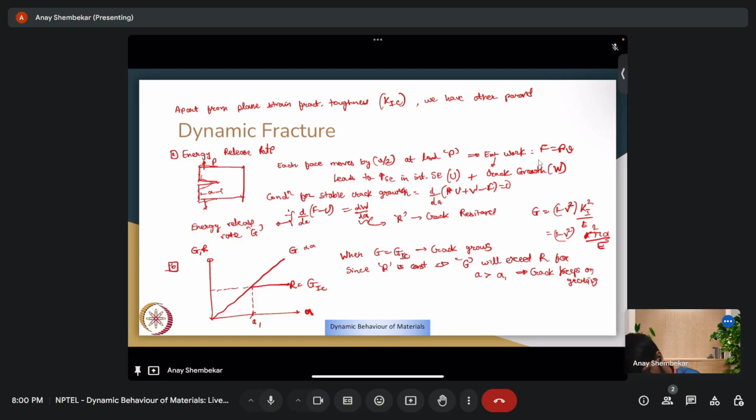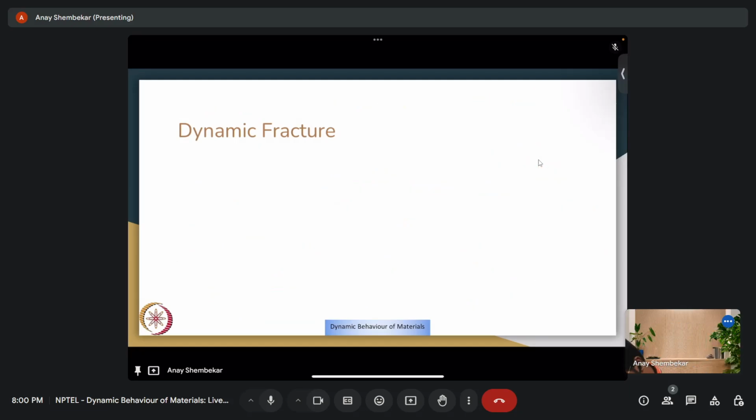So, an important point is, when plasticity is high or considerable, which is the case for ductile materials, J integral can be used. And for linear elastic fracture mechanics for brittle materials, J equals energy release rate G. Pertaining to dynamic fracture, there are certain unique features.